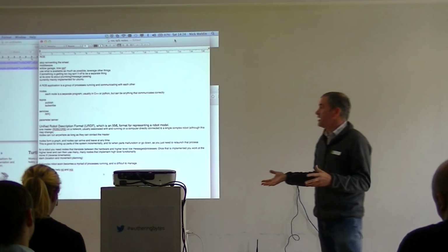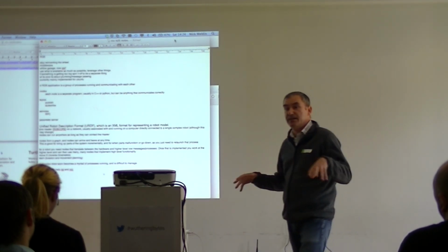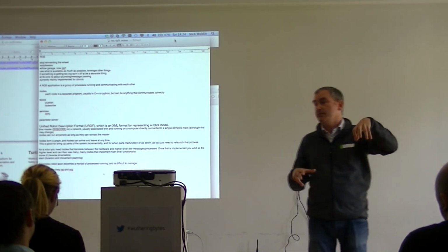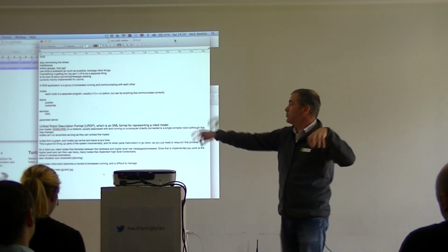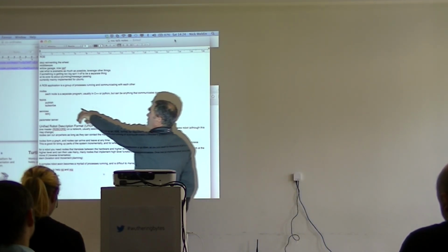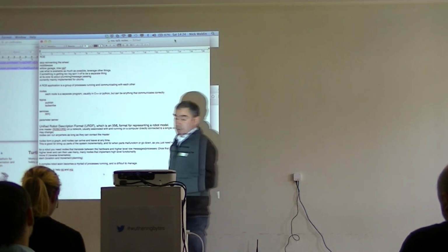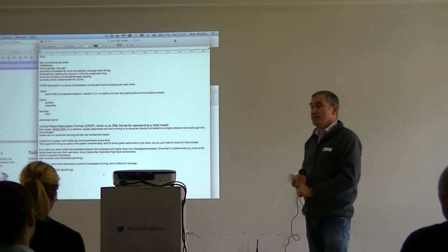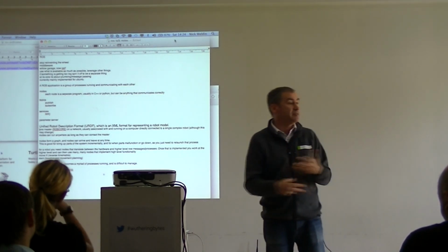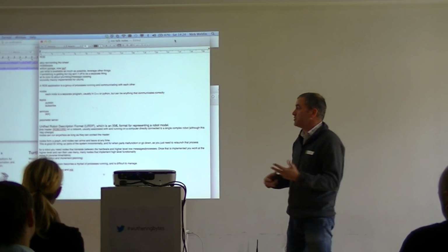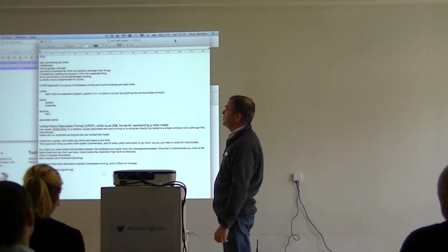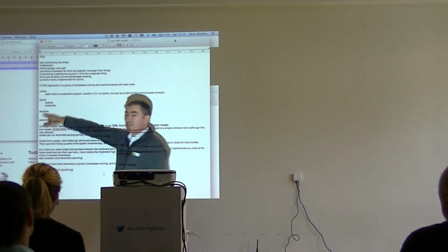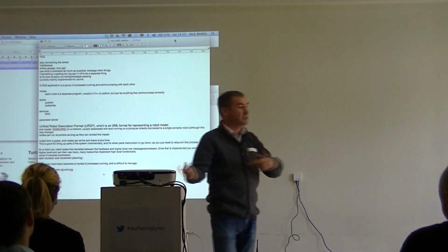And basically a ROS application is a group of processes running and communicating with each other. So you have a process called ROS core, and you launch that, and that's a server. And anything else that gets launched is called a node. And basically they're all separate programs, usually in C++ or Python, but you could write it in anything you want as long as it sends the messages in the right format. But all the code that they produce and show is C++ and Python. And nodes can publish or subscribe to topics. That's how you can pass messages backwards and forwards.